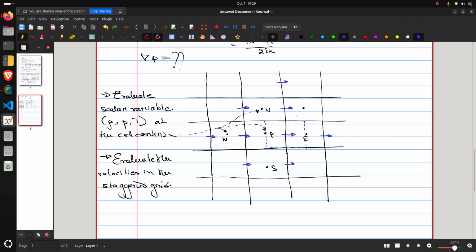We just shifted the grid in the x direction, and this will be the other grid now. Let me just draw it in solid line only. So this is the cell in which we compute the x velocity. And what are its neighbors? Its neighbors are these cells, right? So this cell's neighbors are this one, this one, this one, and this one.